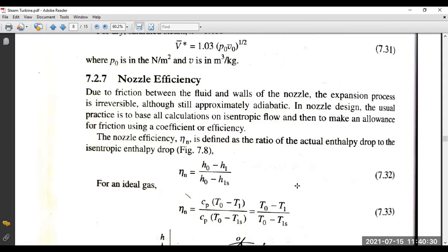The stagnation enthalpy or stagnation temperature is now related to the enthalpy and the velocity of the moving fluid itself. So we are just assuming that the flowing fluid, when it is steadily flowing, is brought to rest by some artificial means, but without doing any work or without any heat transfer.